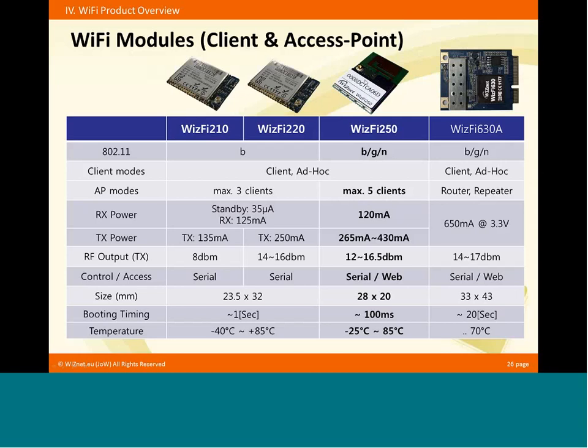But the standard application for those client modules would be that this is a station, and it will connect to an access point, and you have your MCU attached here, and you can transfer data serial to Ethernet to the server. And yeah, we have those RF data. We have a serial configuration port, and we have a Webserver inside for configuration. So you can configure this config tool on the web page and with serial commands.